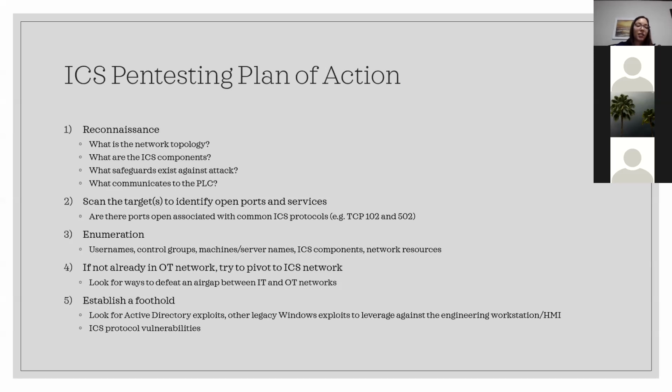After that, you'll do your port scanning, try and see if you can find any open ports associated with common ICS protocols. And when I say scan the target, I'm usually referring to engineering workstations or HMIs. So those are usually the most likely to be connected to PLCs, and they're usually juicy targets.